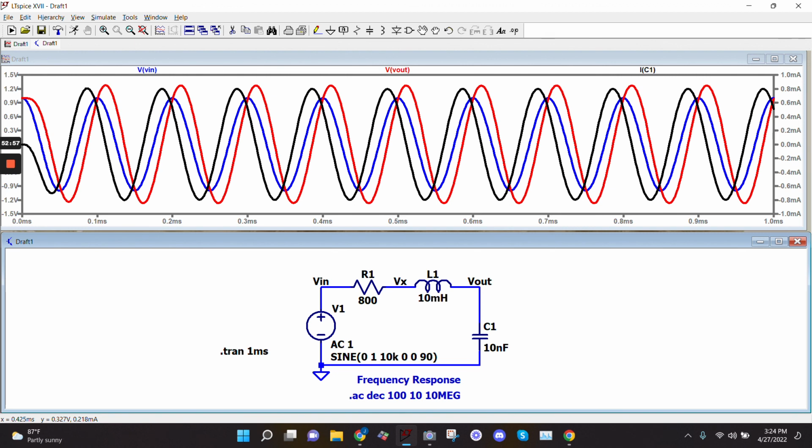You need a very special type of probe to measure it, because they use what's called a current probe. That's kind of self-explanatory, but what it does is it clamps. If this is the wire, it'll clamp around the wire, and it's measuring the magnetic field around the wire and converting it into a current, because magnetic field and current are related in inductive circuits.